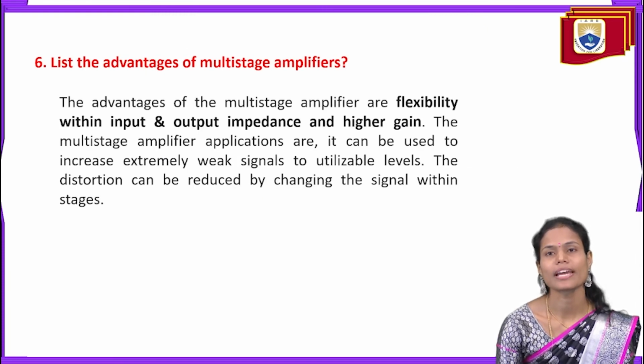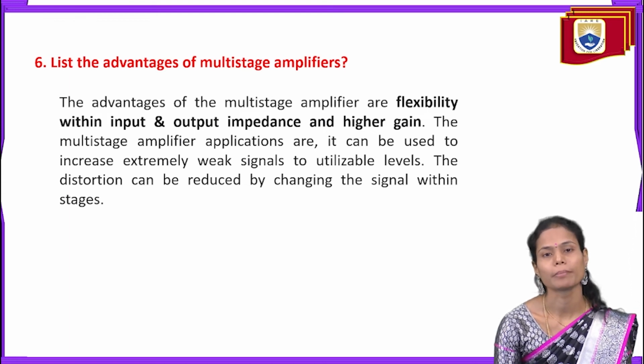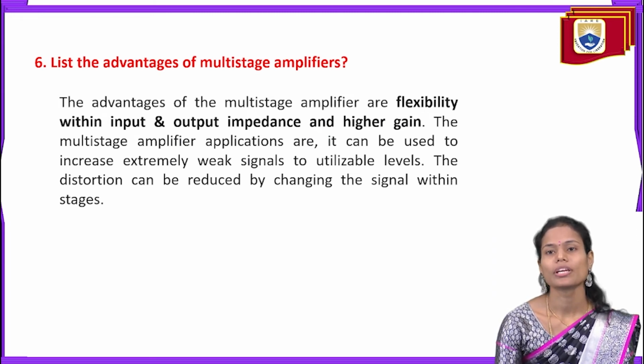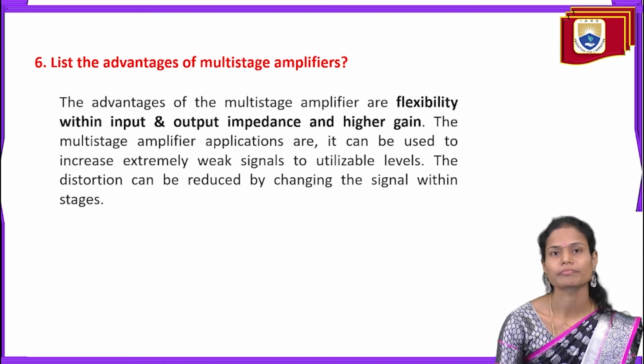And next, list the advantages of multi-stage amplifiers. So multi-stage amplifiers provide very high gain, very high input impedance and low output impedance here. So these are the major advantages of multi-stage amplifiers. That's why we can utilize these multi-stage amplifiers for high frequency applications.